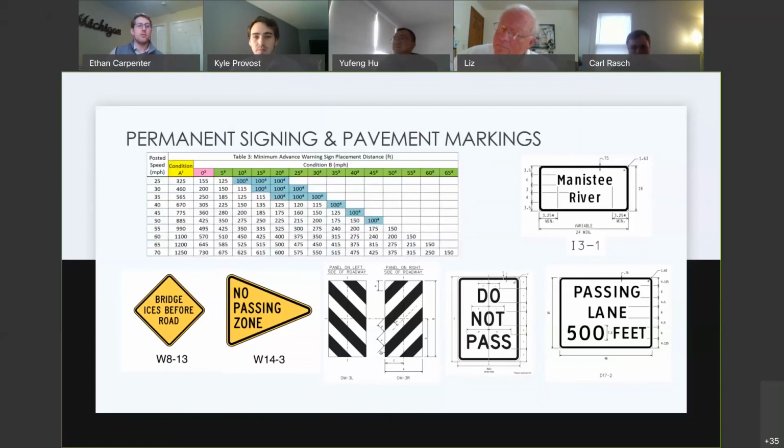Warning signs were determined through MDOT design placement application guidelines to be placed at a distance of 360 feet from the bridge approaches for a posted speed of 45 miles per hour. If any warning sign is located within a curve at the 360-foot specified distance, they are to be moved before entering the curves to allow drivers to prepare for the approach.